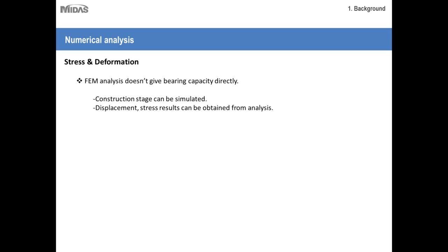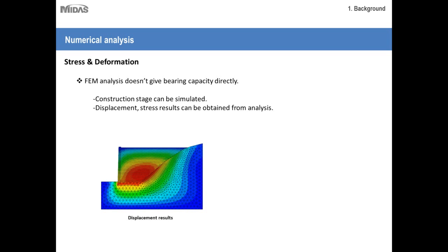What it does is it helps you to simulate construction stage analysis. It gives you displacement and stress results. So here you can see the displacement results of a segmentally constructed retaining wall with reinforcements, and you can see the red zone is right here instead of being somewhere here where you would expect maximum deformation otherwise.